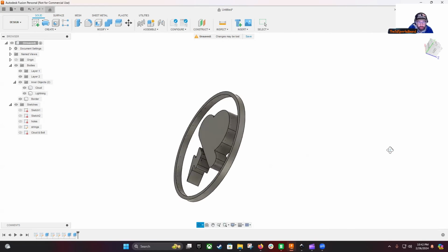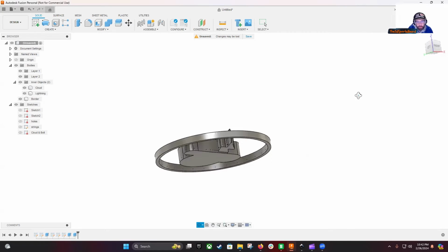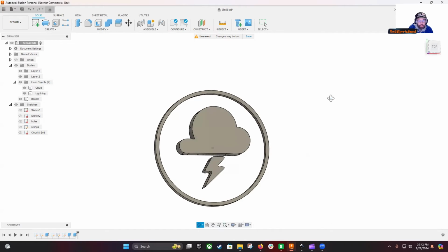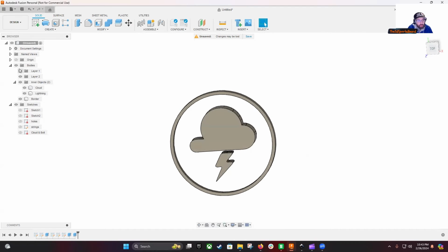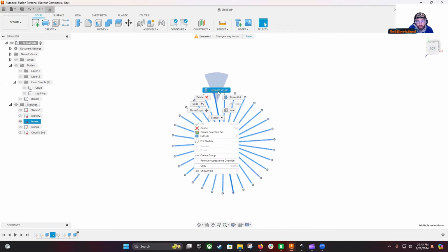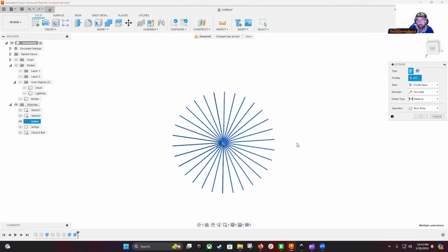And it's going to cut this perfectly. So now we see we have cut lines all throughout, right? And so what I do next is I turn our bodies back off. We go back over here. And then you could right click and repeat extrude, or you can hit E, doesn't matter.